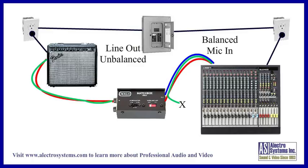Therefore, we can eliminate the ground loop by simply disconnecting the ground from the DI box end of the balanced cable. Most DI boxes have a switch to do this. As long as the shield is still connected at the mixer end, we maintain our noise protection for the cable. There is no safety hazard because we are not affecting the AC grounding. There's one more thing that the DI box does for us.